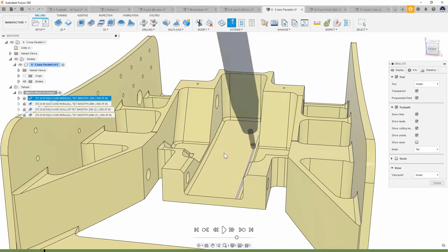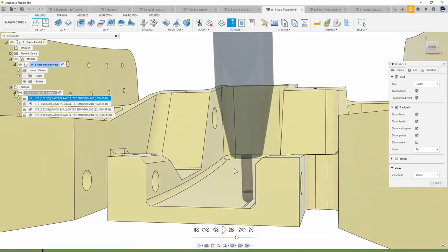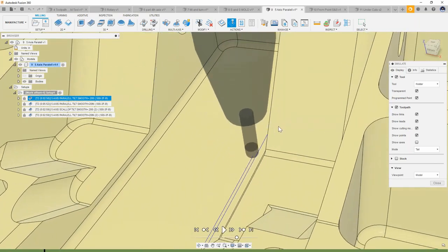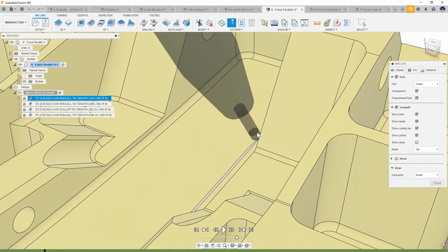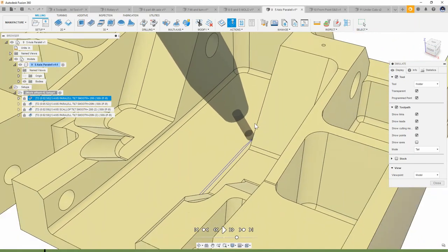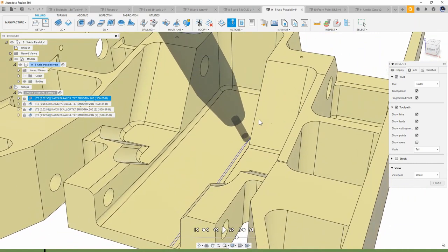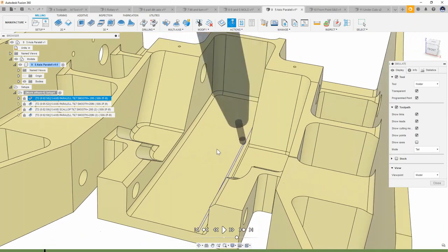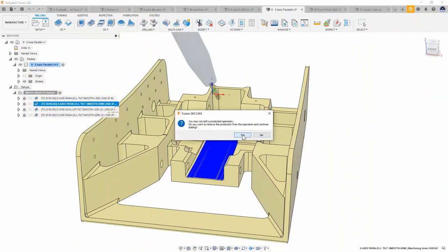When I go in here, even this first motion, obviously it's not colliding, it's standing the tool up, the tool is free and clear of the part. When I get over here to where this wall is, it's going to jerk the tool out of the way. Now that jerk motion is not very desirable. It's not going to look good on the machine. It's probably going to scare us the first times that happens when the part just automatically tips out of the way. And it's not going to produce a good surface finish, to be honest. So what we would want to do is there's a specific setting in here. We'd look at this one that I have here.